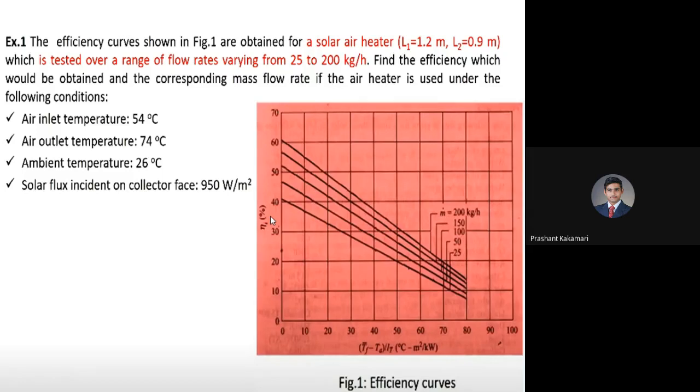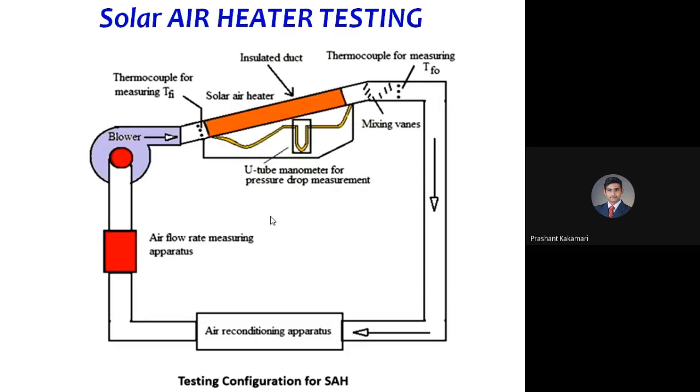But in the air heaters, if you see in this curve, the air is not completely in contact with the duct always. We can assume that air is always in contact with the duct perimeter inside, but it is not sure. It depends on different conditions. If the blower is blowing a very low air quantity, or the mass flow rate is very low, then the density of the air also matters, and depending on the temperature, the contact of the air with the duct will vary.